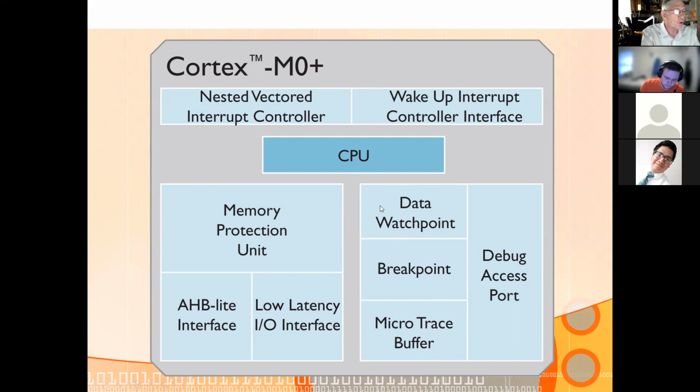However, in order to do that, you do need a different programmer than the OpenSDA connection we're going to use. So you would need to actually buy a separate programmer to plug into it. But this debug interface is really pretty powerful. And the nice thing about it is you don't have to specifically compile for debug. The debug is always available to you. Unlike on a low-level PIC chip, you do have to specifically compile it for debug.